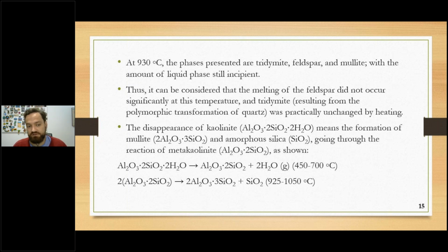The disappearance of kaolinite means the formation of mullite and amorphous silica, going through the reaction of metakaolinite as shown on the two reactions below. Metakaolinite transforming in mullite and water.